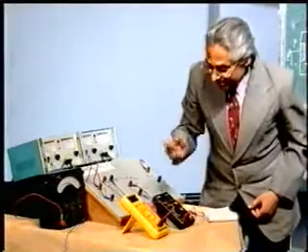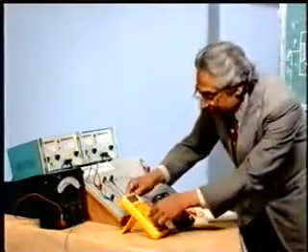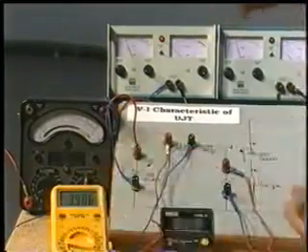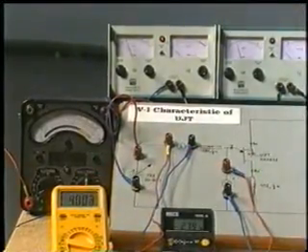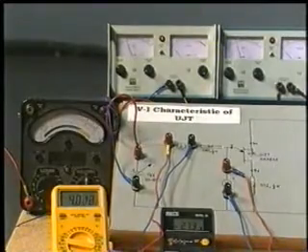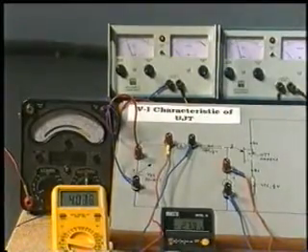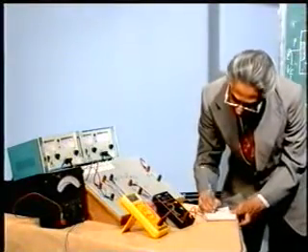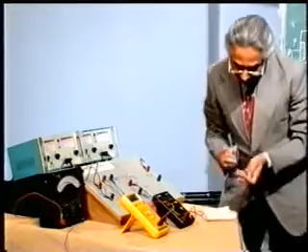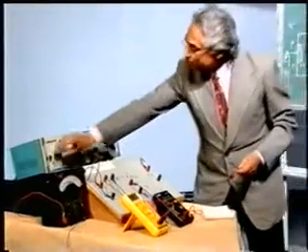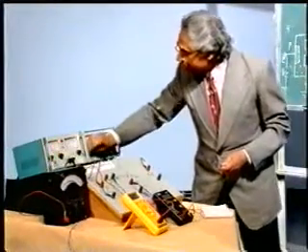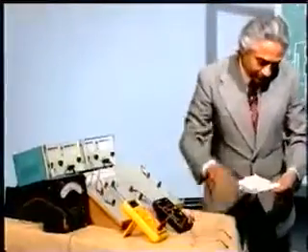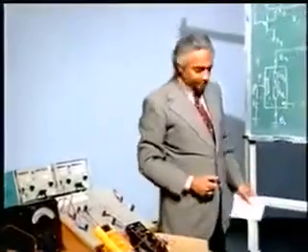The value is, let me change this, yes, it is 3.994 and it was 7.9 volts there, 7.9 volts and about 3.944, say approximately 4 milliamperes. So with these readings I can, of course I put it to 0, put it also to 0, and let me note down the values for you. With these values we can plot the VI characteristic.